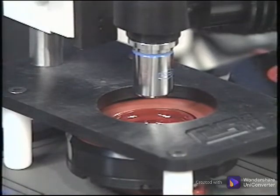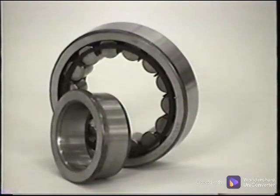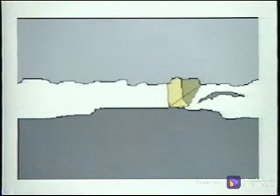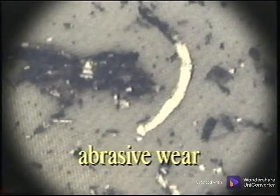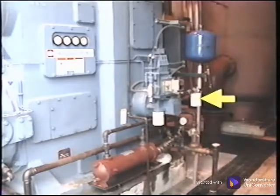A system typically has a 2-body system, that is, 2 components of a bearing, for instance, are separated by a thin oil film. When a 3rd body, such as dirt or silica, is in the film, it will cause scraping or gouging of the bearing components, creating a long, narrow particle similar to a machining swarf. When this abrasive wear is present, find the source of the abrasion and remove it. Check the breather for possible influx of contaminants and make sure the filter is adequate for the application.